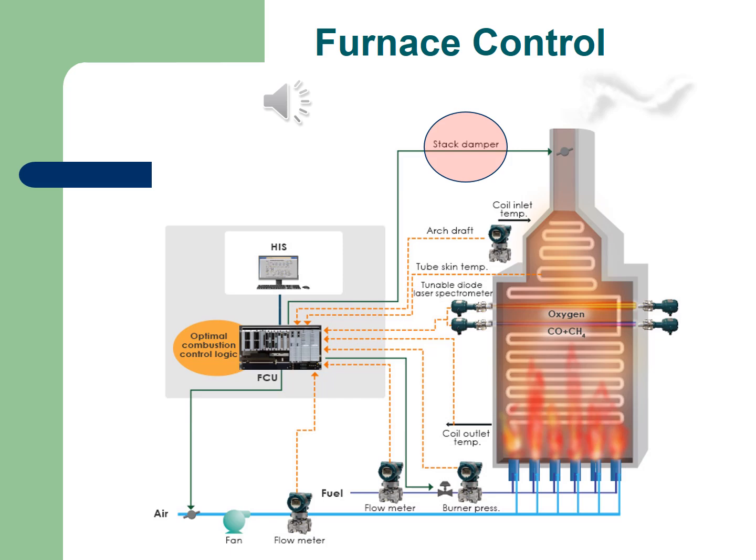If we look at the red colored circle, the stack damper can be controlled via a controller. This is important for the amount of flow of air that goes through this furnace, and that will again have an effect on how much heat is in actual fact exchanged.